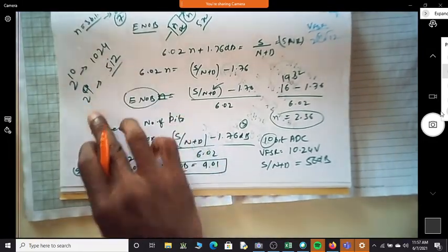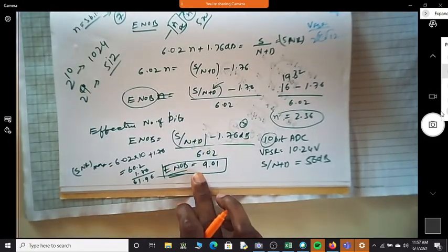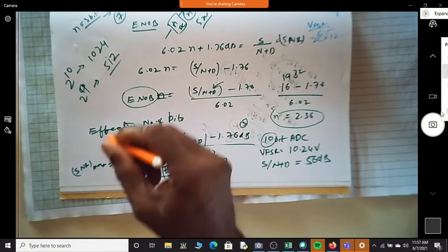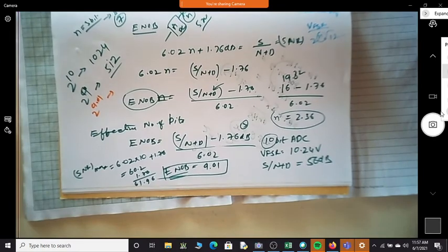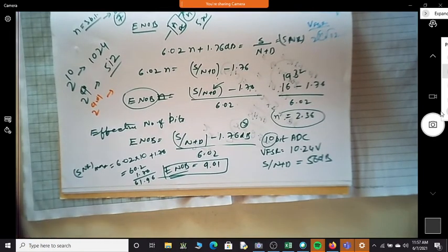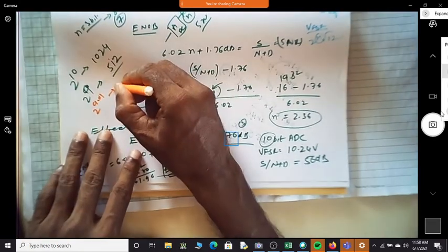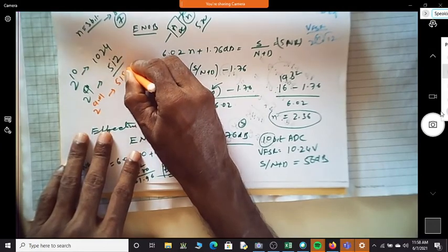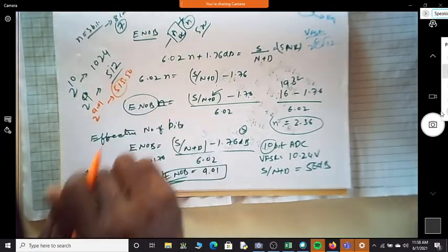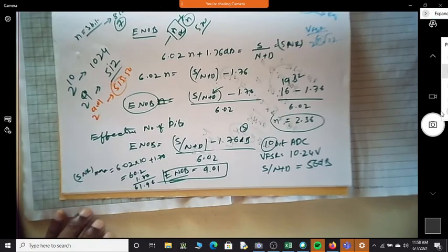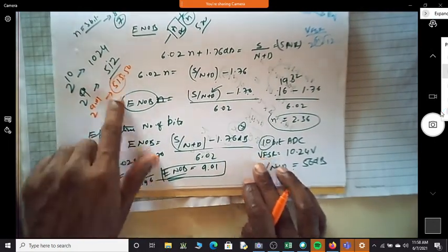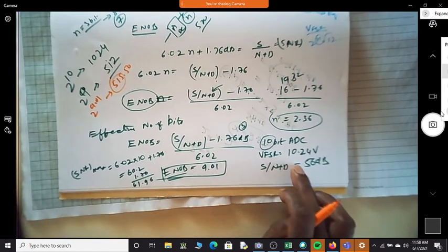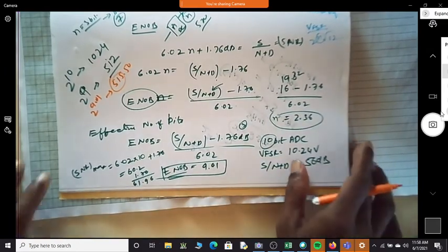So instead of exactly 2 to the power of 9.01, what is the exact number? 515.56. You'll get 515 combinations instead of 1024. You'll be worried, why am I not getting some combinations? It's because the signal to noise ratio is very poor in that ADC.